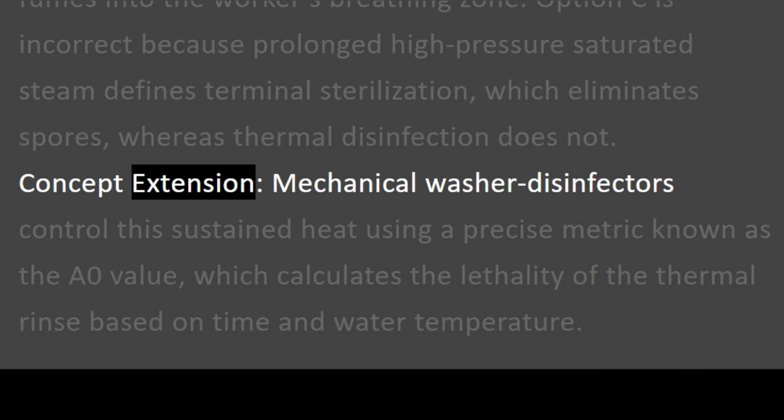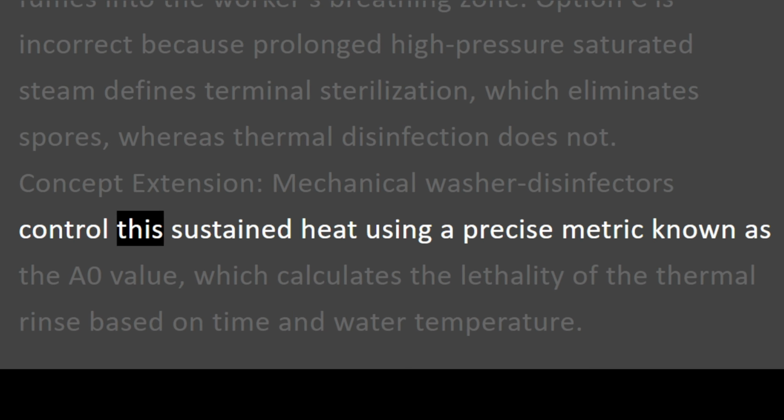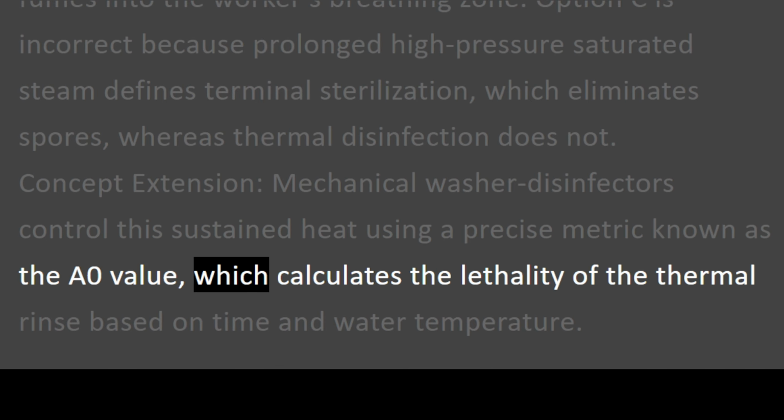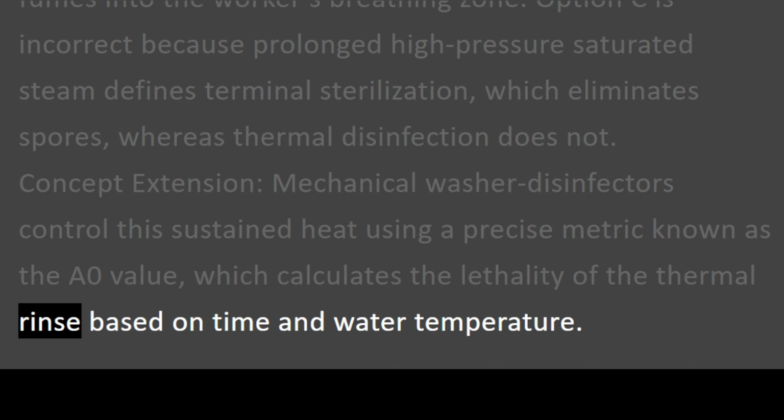Concept extension. Mechanical washer disinfectors control this sustained heat using a precise metric known as the A0 value, which calculates the lethality of the thermal rinse based on time and water temperature.